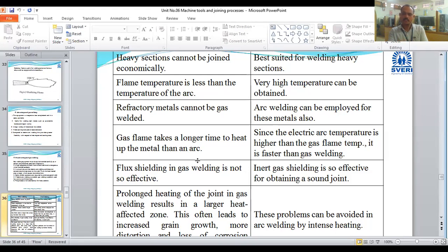If you check, at the time of joining with arc welding, they require some gap between the workpiece and the electrode. A little gap has to be kept between the electrode and the workpiece. It is for that bombarding of electrons. For that, skill is required from the person: how much gap we have to keep there, and how to maintain that gap.